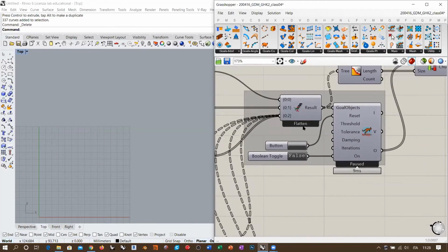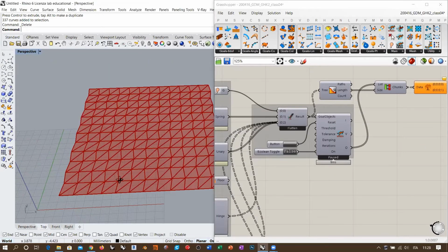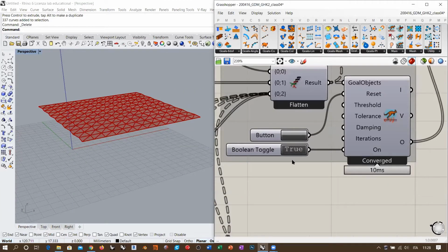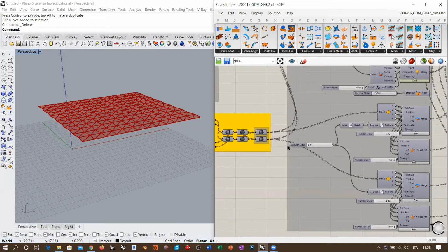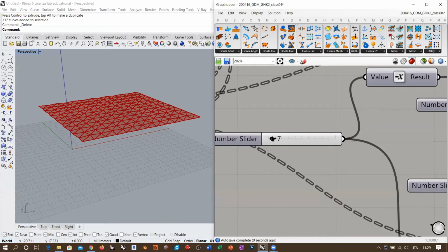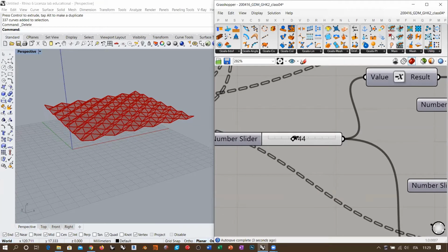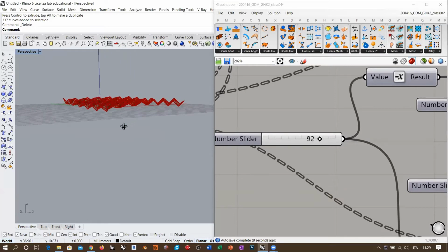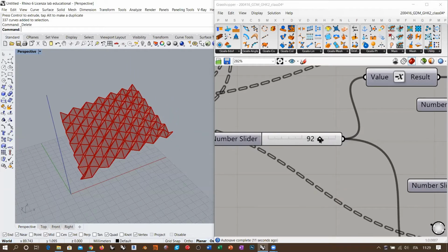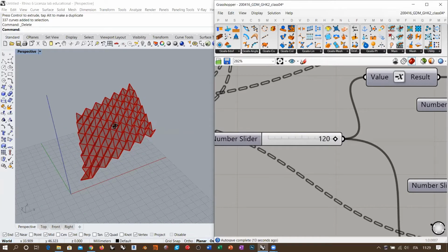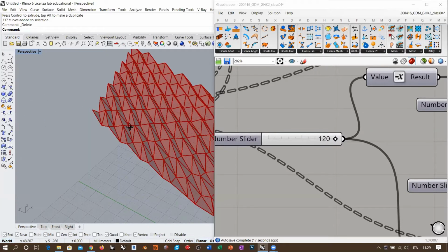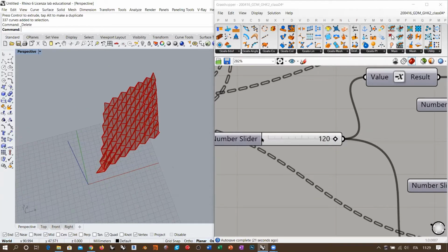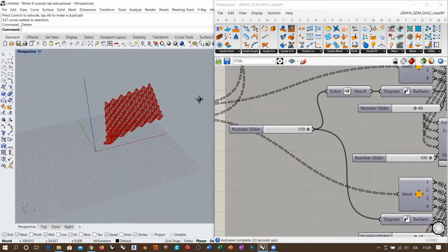Now, in this case, if we go here and visualize the result, let me go into perspective because I wanted to see it from the diagonal point of view, and run the simulation, and go here, take the rest angle, and start to increase it. So if we increase it, you see that now the behavior is exactly what we expected. Okay, this thing is starting to fold along the diagonals. And if I increase it, increase it, increase it, you see that this thing starts to bend, to fold properly. It is packing along the opposite diagonal. So basically, this is the correct behavior.